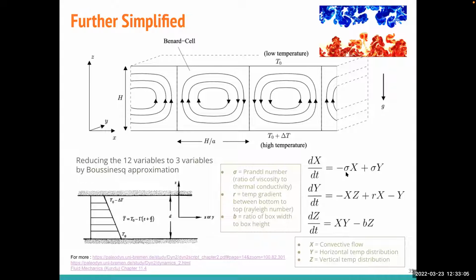coefficients which are controlling the behavior of the system. If your coefficients are not right, it means that your viscosity is not right. Okay, so the first one is sigma here, the Prandtl number, which we have talked about in 4210, I guess. So the ratio of viscosity to thermal conductivity. So there are two ways to have heat conduction or heat transfer in here. The first one is by viscosity. We're talking about convection, the overturning. The second one is the conduction, thermal conductivity. So it's the ratio between the two heat transfer, the Prandtl number.